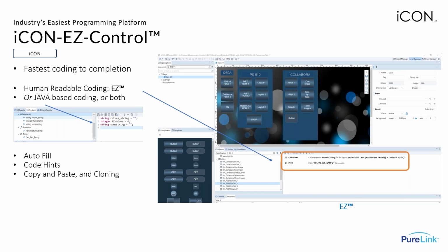And then you have pop-up windows, and pop-up windows again can be triggered either by the user, manual button press, or by a scheduled event. Maybe at a certain time of day you want a message to appear, or it can be triggered by a conditional event. For example, you lose communications with one of the devices you're trying to control, so a pop-up window appears saying unable to communicate with a device.